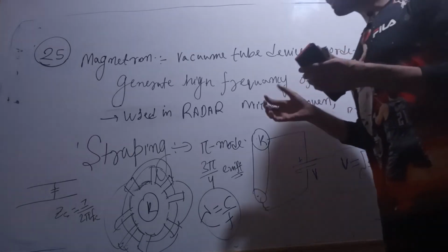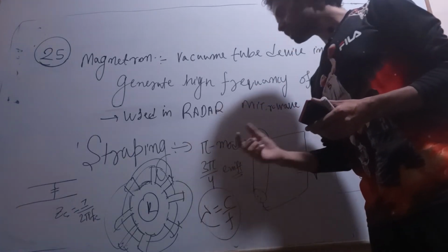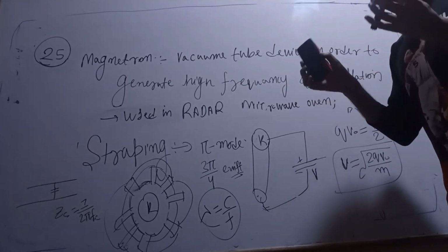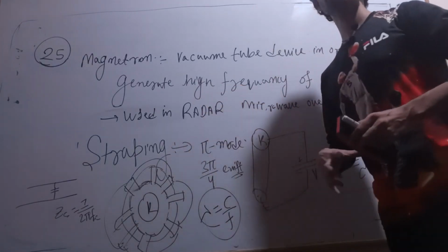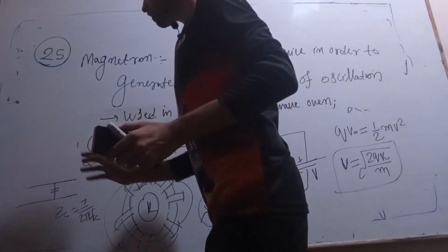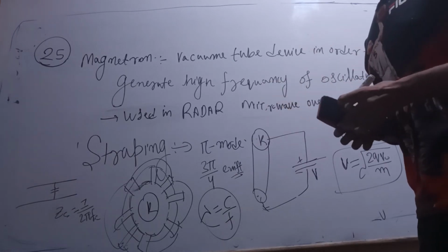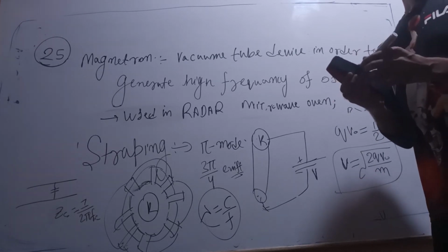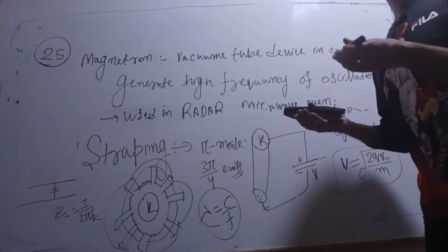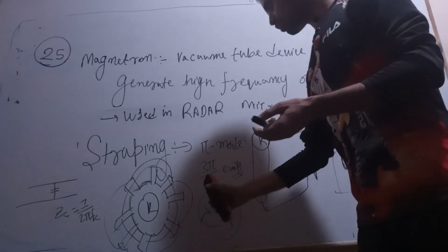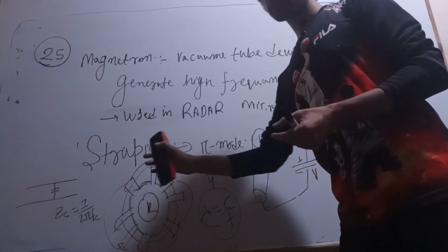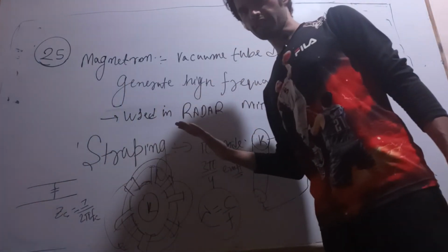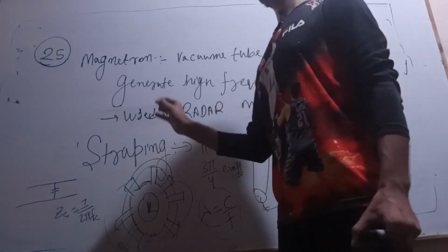At a certain point, the wavelength and the length of the component will become comparable to each other, and at that time this element, this conductor, will start radiating at very high frequency, because both the wavelength and the length of the element come into comparison. Therefore, this conductor will start radiating. So this is radiation; radiation losses will occur at high frequency.